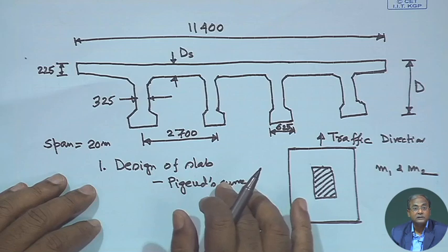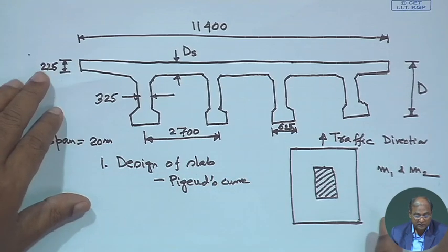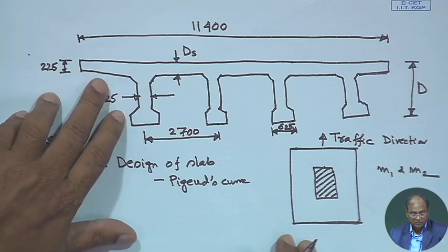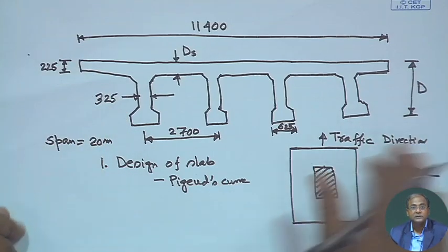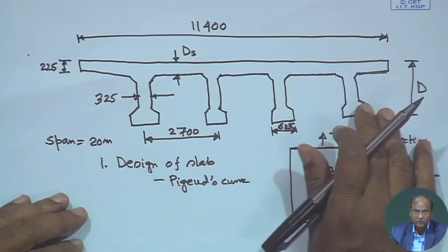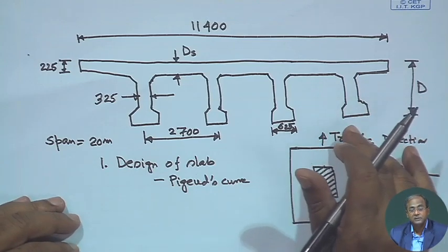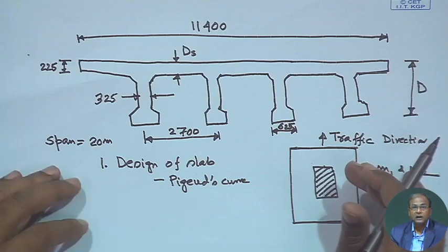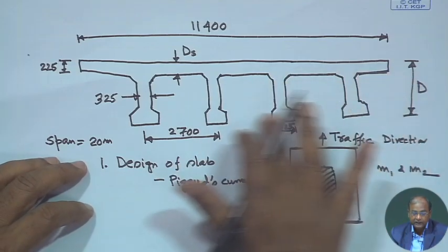So, this is your that step, and on the basis of that, in most of the cases we check the section. Most of the bridges are so standard nowadays that you can find 20 meter, as I have told you, RCC beam means 20 meter span, and it can go from 18 meter to 22 meter like that. So, we make the configuration,